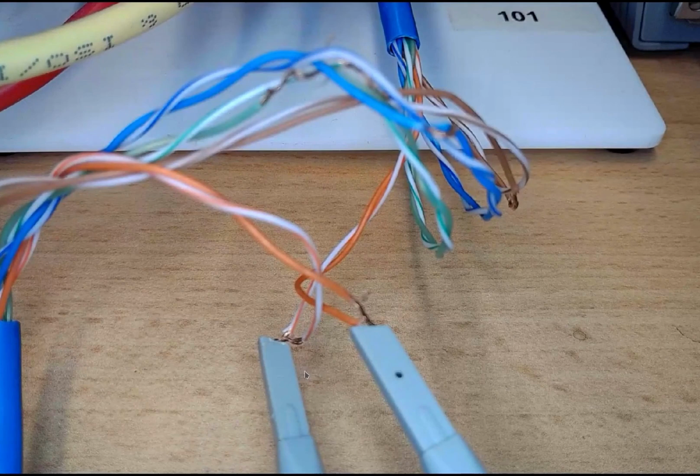I'm sure at this point the electronic engineers out there are shouting, what about your grounds? Your grounds, you fool! You're connecting your scope probes to an isolated voltage. There's no common ground. And yes, you're right. But I was trying to show here, by connecting the scope up this way, the advantage of a differential pair. How we can remove that common mode noise. So yeah, I know it's a bodge. The grounds for these scope probes were connected to the shield ground of the USB connector. But we're going to ignore that.